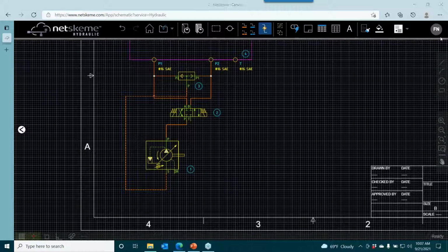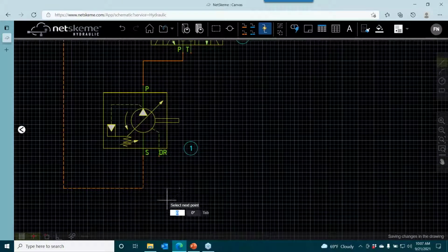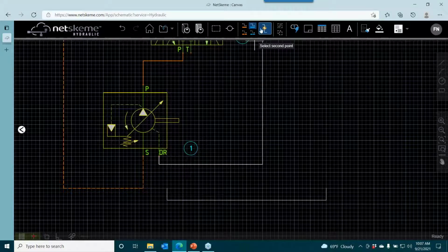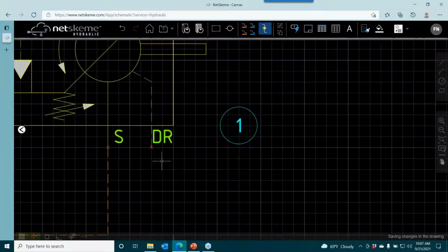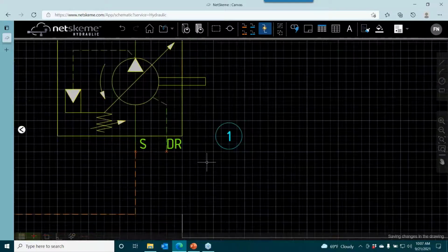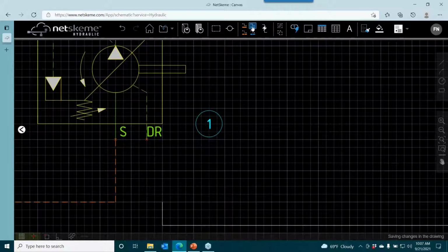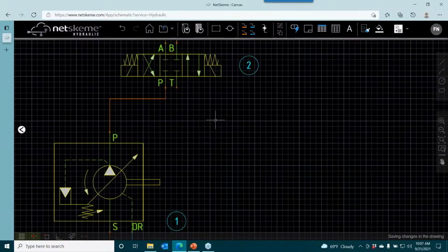We're going to bring in, and actually create from scratch, just a reservoir. We're just going to place something here, and we'll just call that our reservoir. And we're going to have our drain. With drafting elements, or basically anything that doesn't have this red connection cross right here, you're going to want to turn this auto connect off, so that you can manually route any of your connection lines, and then you're just going to hit enter and it'll place your connection line right where you routed it.